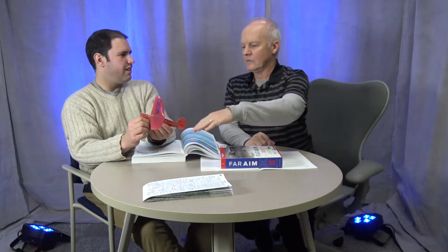where they get up to the top of ground effect, and they're flying along just fine, and then they suddenly stall, because as you get out of ground effect, you have to increase the angle of attack to create the same amount of lift, right? Because you're losing that ground effect. Well, as you increase the angle of attack, you're getting closer to the stall. And if you were already close to the stall in ground effect, and now you climb out of ground effect, well, now you've just increased that angle of attack more. Yeah, I remember reading that when you're taking off, sometimes it'll come up because of ground effect, but you don't have the speed to really climb.